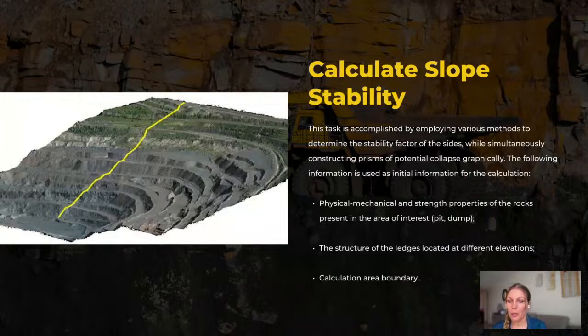In order to determine the calculation area, we need to create two limiting lines that are perpendicular to the edges. These lines can be set using the polyline object, which you will see further in the demonstration. When constructing these lines, we need to make sure that they cross all of the edges along which we need to perform calculation in the top view.